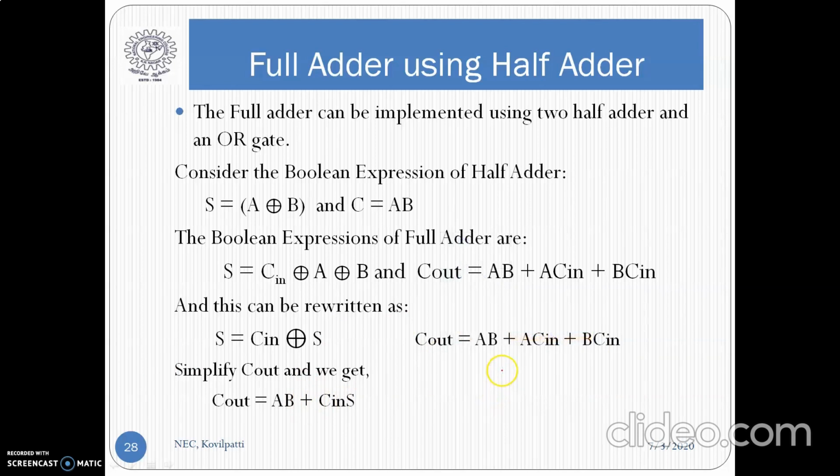So I am having here A, C. For convenience I am writing C, it is only C dash, don't confuse. So we have to add B plus B dash, right? If we add B plus B dash, nothing changes, because B plus B dash is always equal to 1, that we know, right? That is our complement law. So if we multiply this, what do we get? We get 2 terms, right? ABC plus AB dash C.